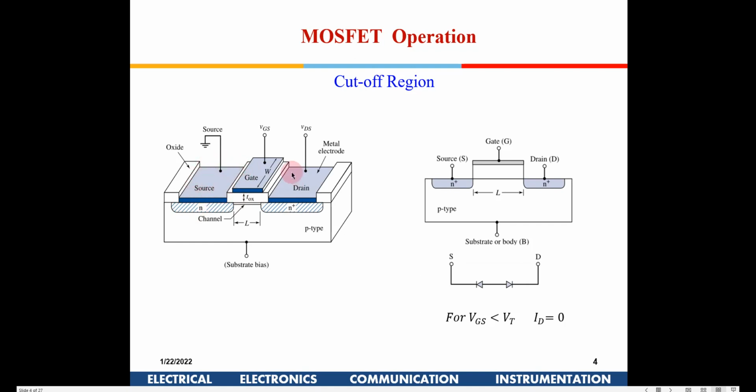We open these two areas, deposit silicon only on the gate area, and then we implant the N regions. Some amount of N region gets diffused below the gate also, so you will have a little bit of an overlap out here.